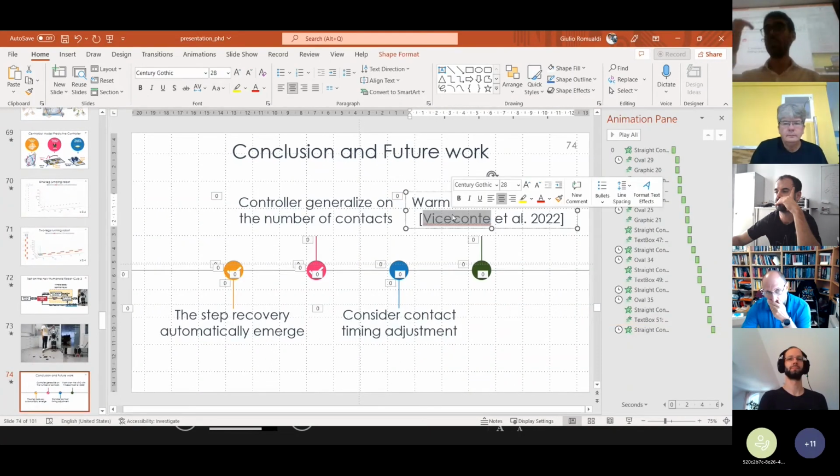In this work, Viceconte 2022, the motion of the human is generated by a neural network, and then we can directly remove the two-step planner, and directly implement the centroidal MPC and then send the commands to the robot. Implementing all of it in a unique MPC controller, I think it's still really hard to have it online and adjust the position of the footsteps online. It's really hard.